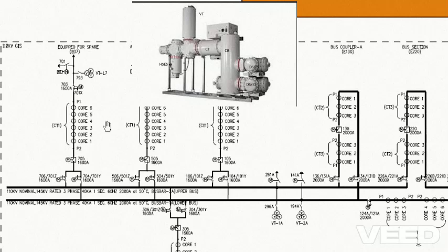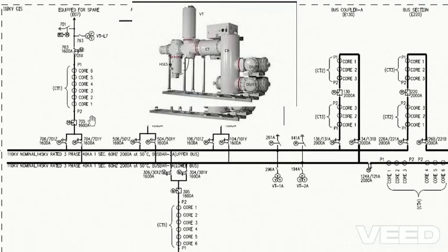For example, the circuit breaker here is designed for 1600 ampere. Suppose the current flowing here is 1000 ampere or 700 amperes. No one can measure this current, but this CT will step it down to a measurable value.